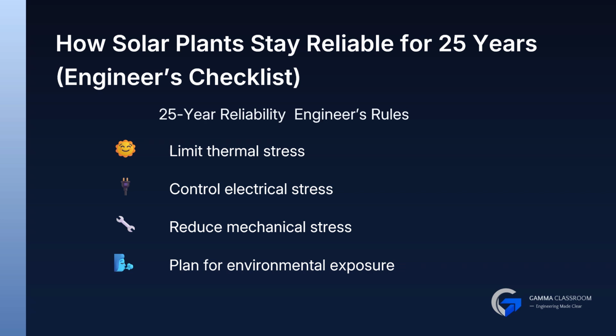Long-term reliability comes from managing stresses: thermal, electrical, mechanical, and environmental. Even when the design is compatible, controlling those stresses is what keeps a solar plant performing for 25 years.